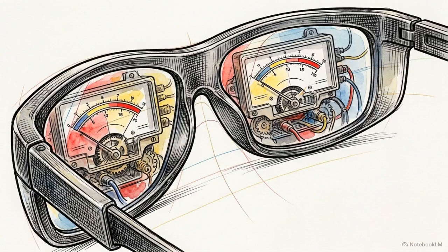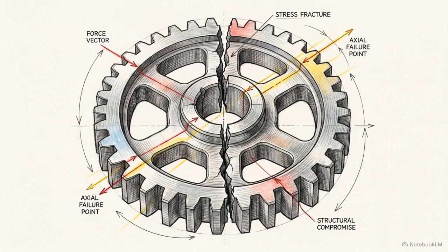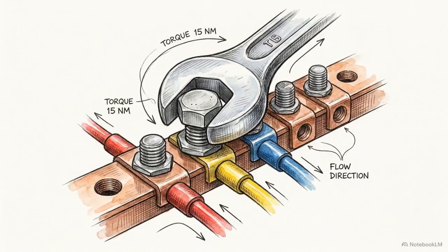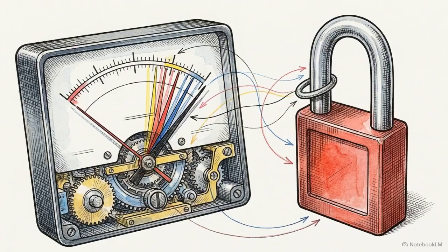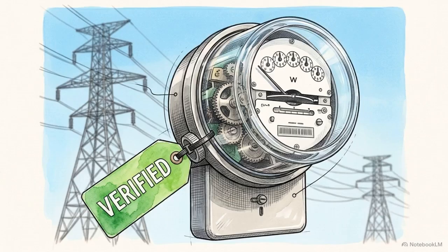Mechanical checks are strict. If an analog needle oscillates, it indicates a mechanical defect. You inspect the terminal tightness. If tight and it still oscillates, halt and fail the inspection. Proving mechanical fidelity across this 3-point curve allows the hardware to be verified for use under live grid conditions.